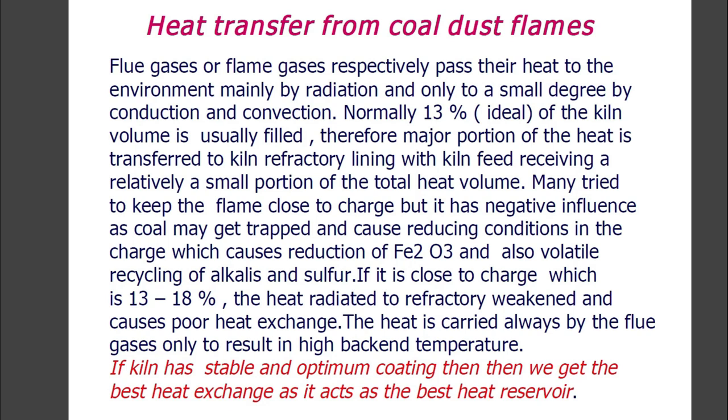Many try to keep the flame close to the charge, but this has negative influences as coal may get trapped and cause reducing conditions in the charge, which causes reduction of Fe2O3 and also volatile recycling of alkalis and sulfur.